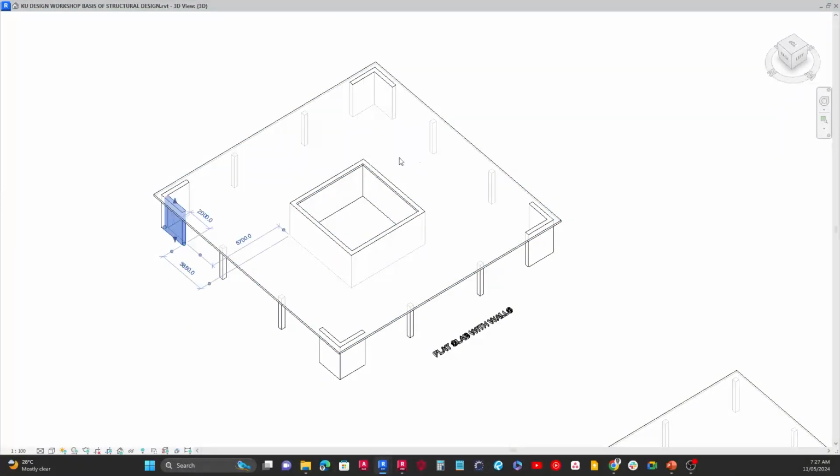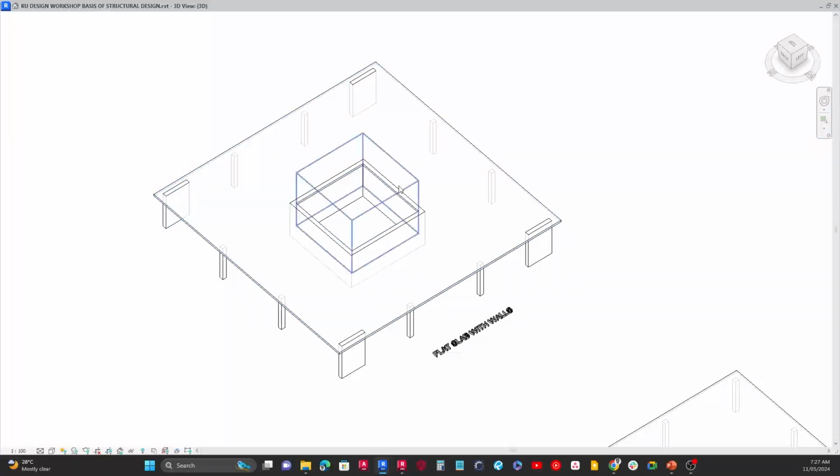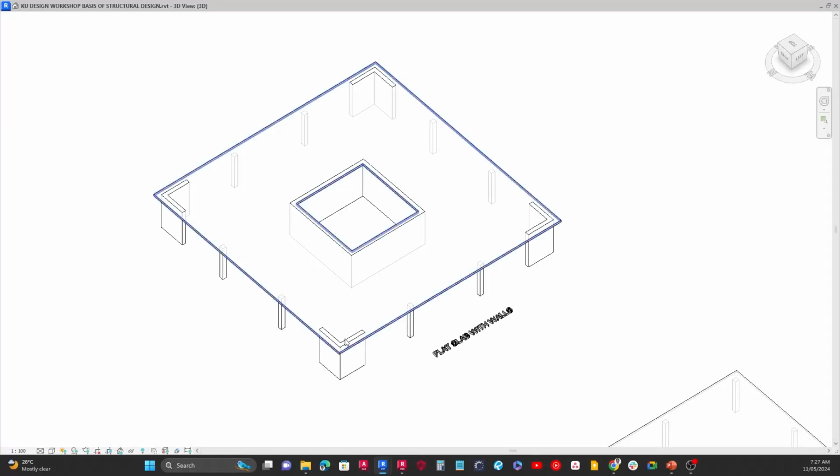If the wind is blowing just in this direction, I can, let me see. Alright, the wind is blowing in this direction, designers will place the orientation of walls like this. But because we can't actually say the wind is blowing in just one direction all the time, that's why we always end up placing walls like this on adjacent ends of the buildings, especially if a building is slender, you want to make sure that it has those adjacent walls.